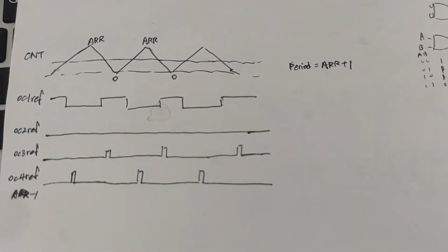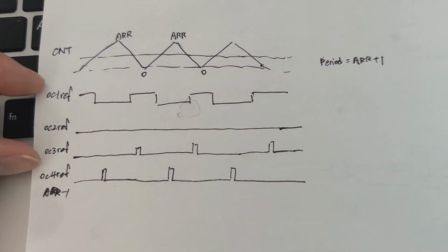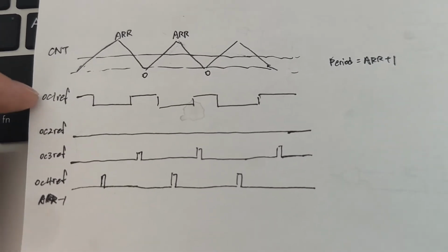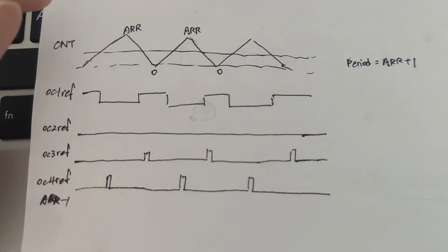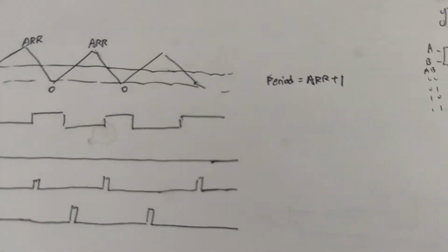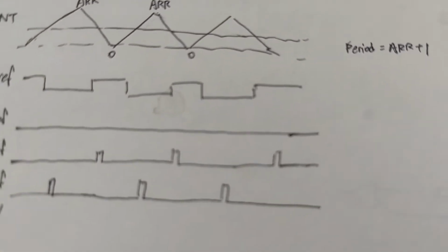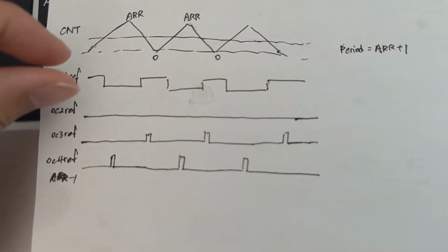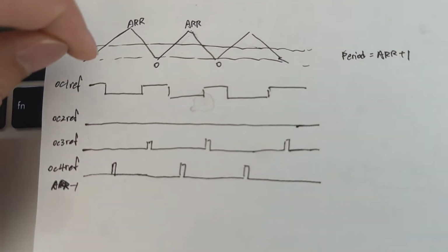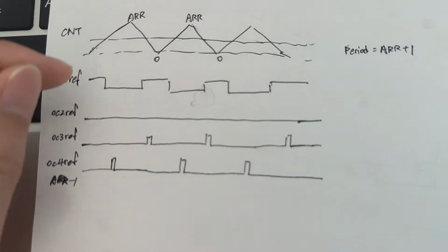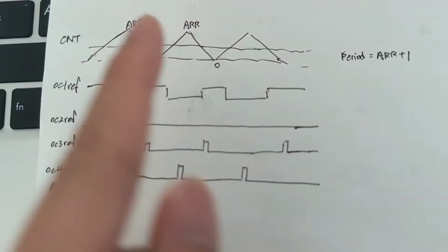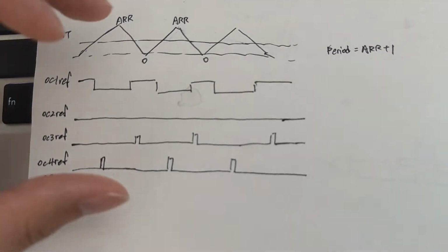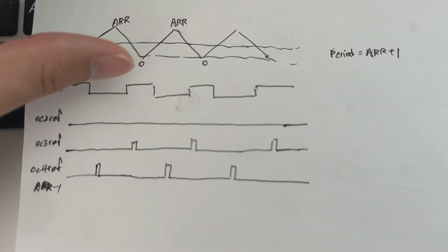And these three are the phase outputs, and this is the threshold register of the 3 phases. By default, in PWM1 mode, the phase output will be high when the counter is lower than the threshold. So during the 0 point, if there is any value, the 3 phases will always be high.